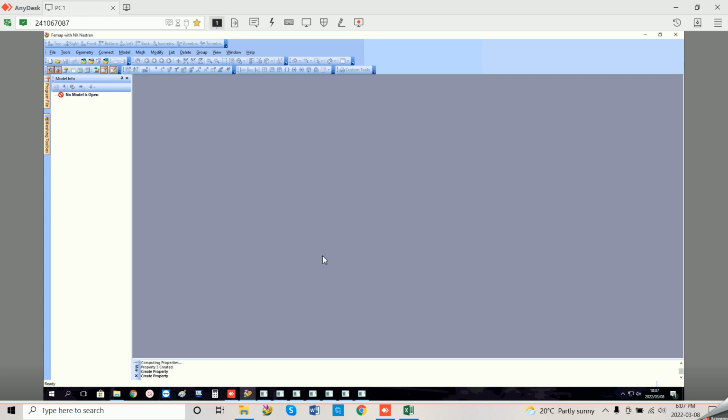Okay, hello. My name's Kevin Braun, and today I'm going to be modeling a singular pile that is embedded within a soil domain. When looking at the geometric attributes of this model, the diameter of the pile is going to be 400 millimeters, where the total length of the pile is 7 meters, where 6 meters of the pile is embedded within the soil, which means that 1 meter of the pile is going to be sticking out above the soil surface. The total depth of the soil domain is going to be 8 meters.